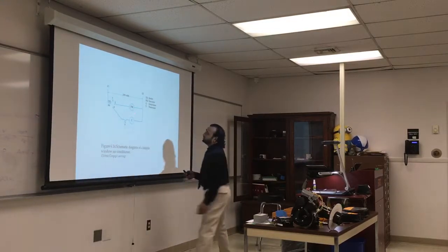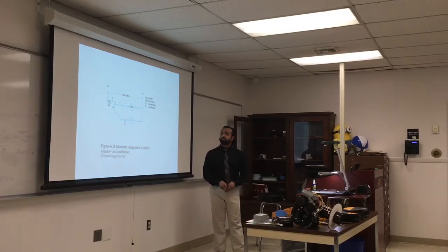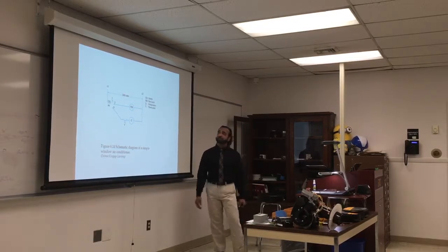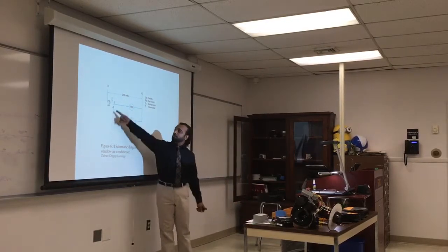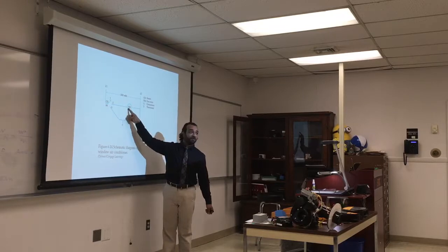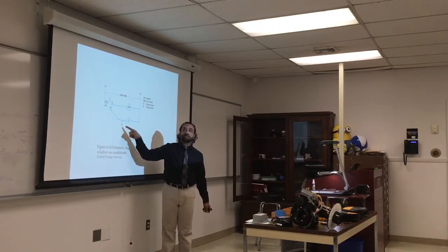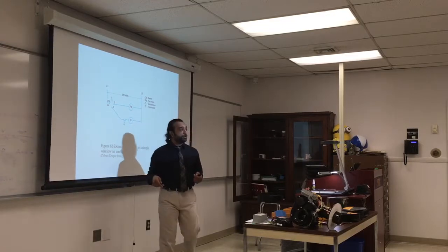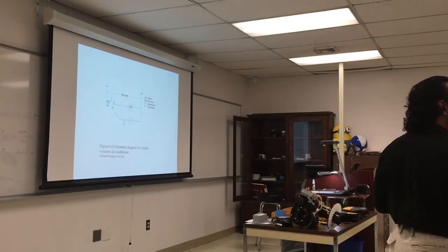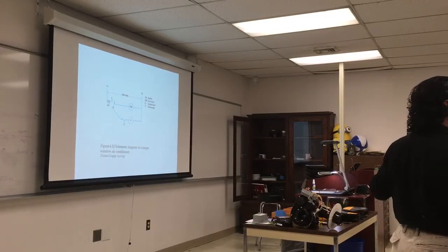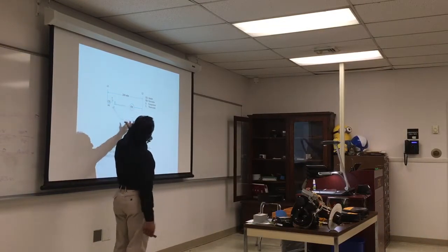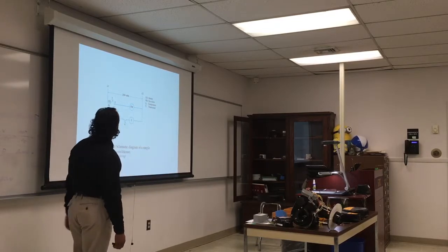This is a small, simple air conditioning system. Very, very simple schematics. If you notice, they don't put much in there. They're telling us the equipment, how it is connected, as simple as possible. Switches, this is an old model, 240 volts, and this is the switch on the board. One turns the fan motor, one has the compressor, and this has the thermostat. If you look at any window AC, there are always 2 knobs, right? One for the low and high temperature, that's the thermostat, and the other one is fan, cool, high cool. So it's going to control the fan and the compressor. So this is a very simple air conditioning unit.